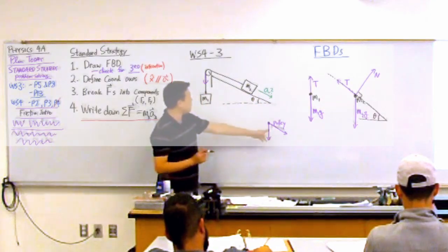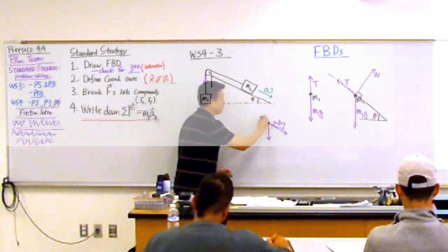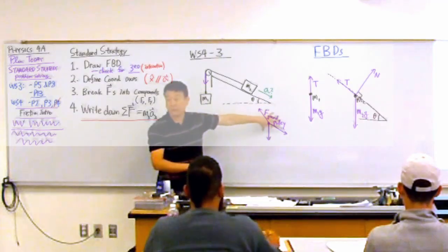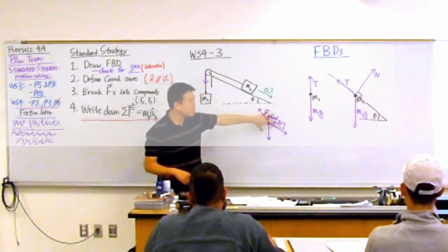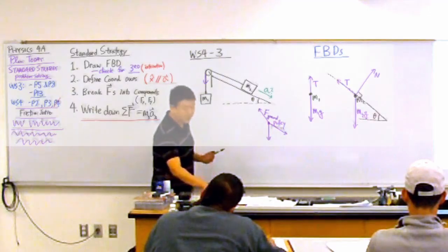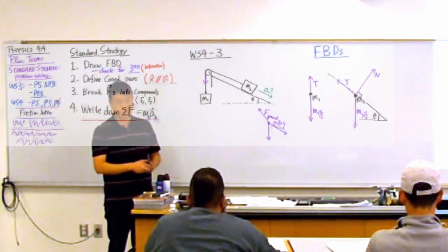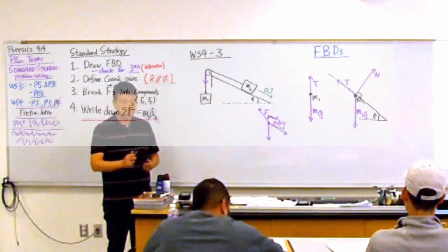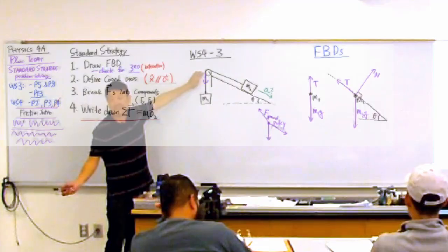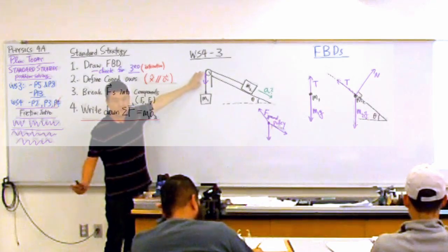But the pulley gets complicated. It's attached to the ramp, it's attached to the ground. So there's going to be some other force of the ground that's going to keep the net force at 0. Which is why if you didn't want to draw it, that's fine. It doesn't add anything. So for the purpose of our current discussion, we can say tension is an external force. That's just the code word saying the reaction force is on the pulley, and the pulley is not in my system. Everyone okay with that? All right, let's keep going.